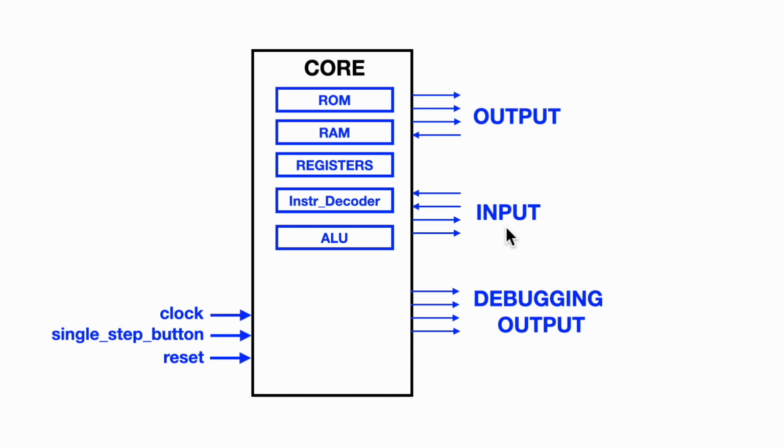and these 4 channels right here will be active in the in instruction. And I mentioned the output control module that we'll use for displaying debugging output. This is strictly a one-way communication. The core will be sending values of interesting things, such as the program counter and the state and the instruction register and so on, to the output control module. So from the point of view of trying to understand the control, we really can kind of ignore the debugging output. Now, of course, our core will have state and it will be clocked, so we have a clock input.